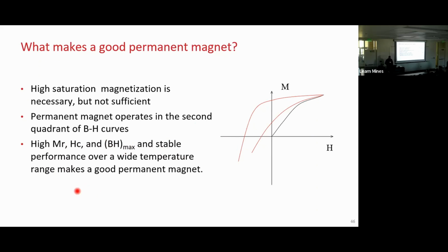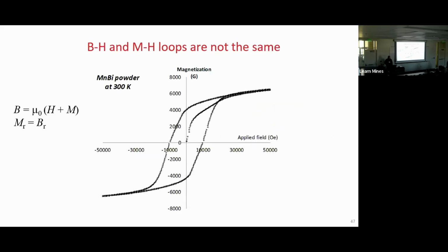I will talk a bit more about how to define this BHmax. There were some people making mistakes about that. Here is a real MH curve. This is a manganese-based magnet that Ames has developed. You apply the field, pull it up near saturation, and come back. You leave something behind. Then with the demagnetization field, you quickly lose your magnetization, eventually it becomes zero. Then with the negative field going down, you desaturate on the way.